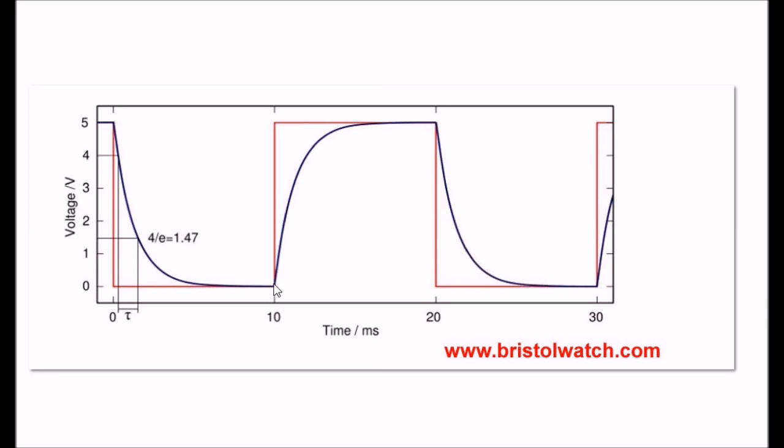Due to all this input capacitance and other issues within the microcontroller I/O pin, you're going to produce a charge curve which is going to play games with switching on the MOSFETs. Then you're going to have a discharge curve that's going to play games again with the MOSFETs, and the faster you try to switch it, the more problems you will have.